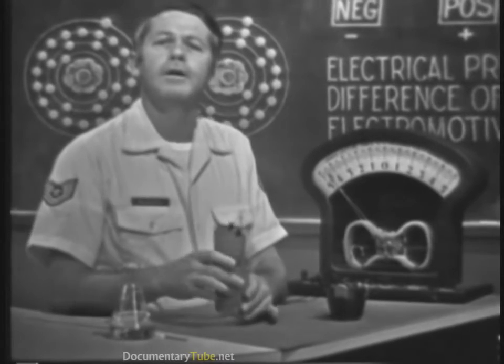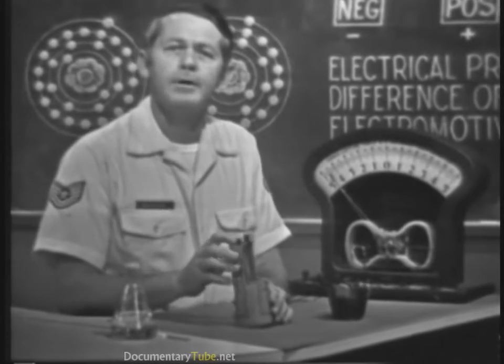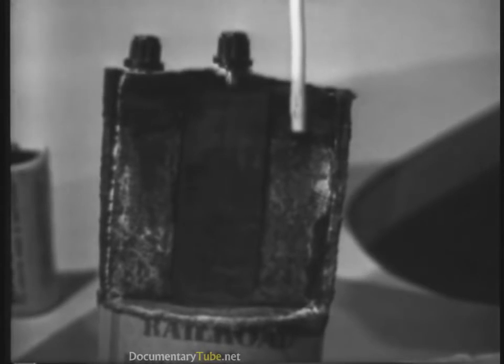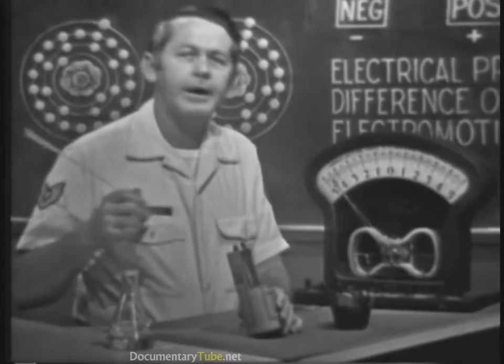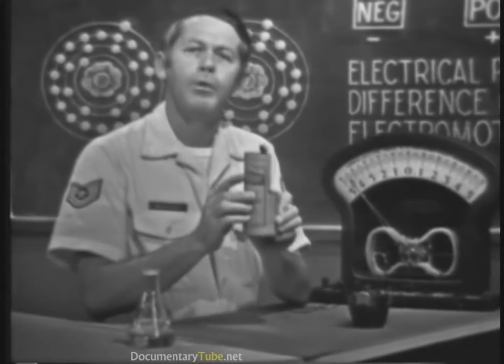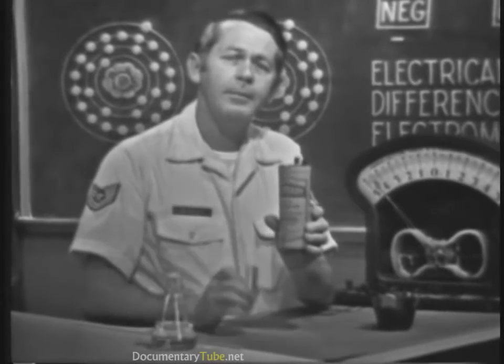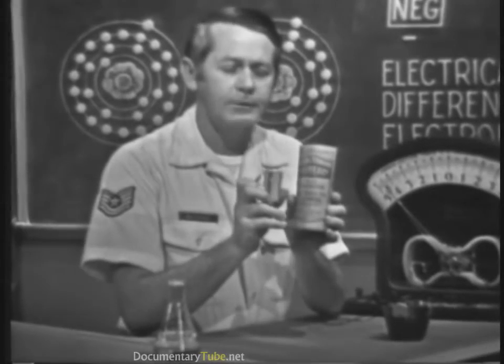Here's another example of developing a voltage by chemical means. Its makeup is about the same as the flashlight battery. Taking a look at it, we see a carbon rod in the center, a zinc case, and a sal ammoniac electrolyte. This battery also supplies 1.6 volts. In other words, the carbon-zinc combination generates 1.6 volts, regardless of the size. The chemical combination determines the amount of voltage.